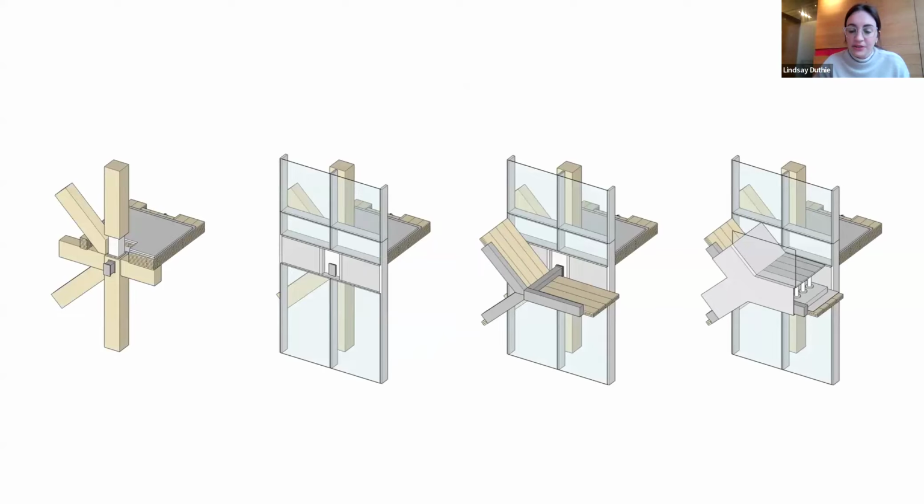We worked with a pre-construction consultant on the project. This brought a lot of value. One of the things we discussed in the early design stage was our construction sequencing. This diagram speaks to that. So we'd have the mass timber structure followed by a unitized facade. This allows the building to be enclosed quickly, which is very important in Rainy City. And then we've got a thermally broken HSS stub out, which acts as the connection point for the balconies, which are then added on after the curtain wall.